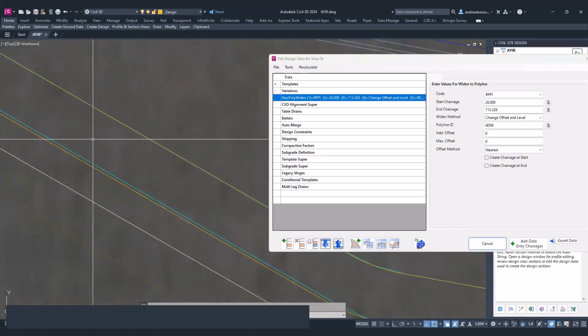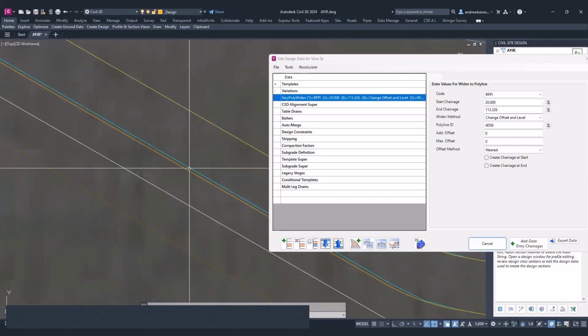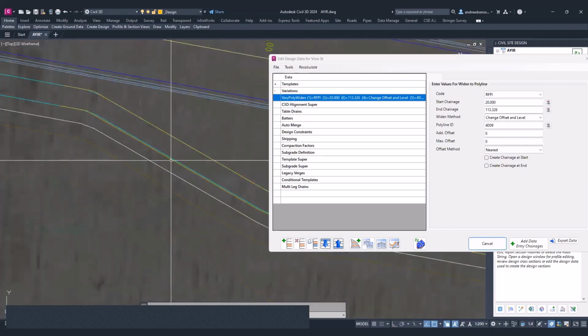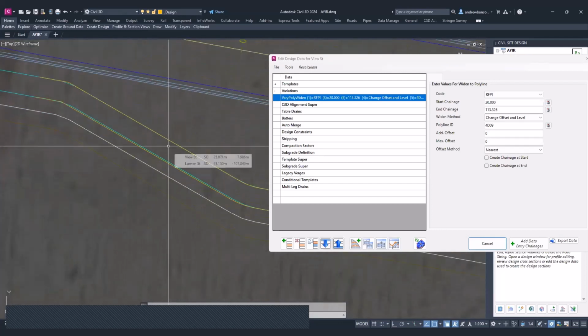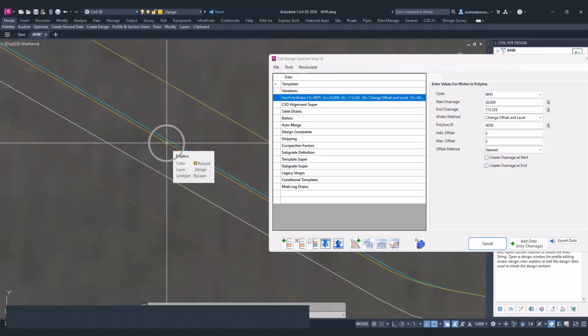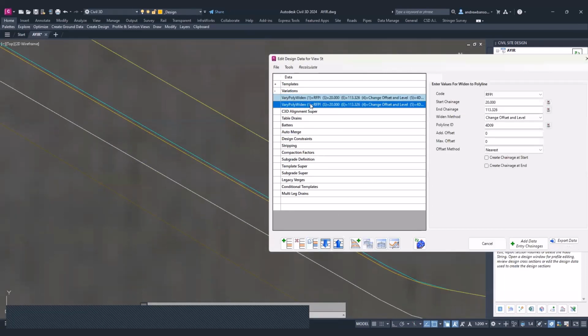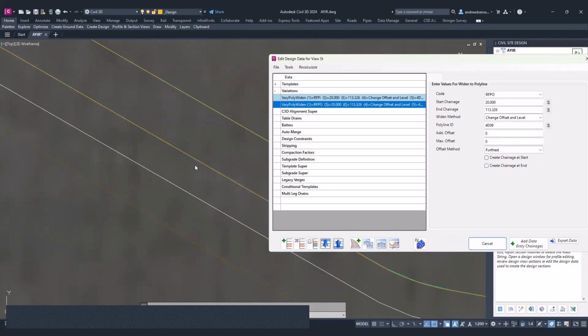Now, if I zoom in really close, I can see the orange polyline, and currently my footpath width is changing here, and that's just because of sectional design. But what I want to do is tell the software that the outer footpath is to match this orange polyline here. So I'm going to create a copy of that variation and say the right footpath outer is going to find the furthest point found on that polyline. If I click on add update, then you can see we've matched that.